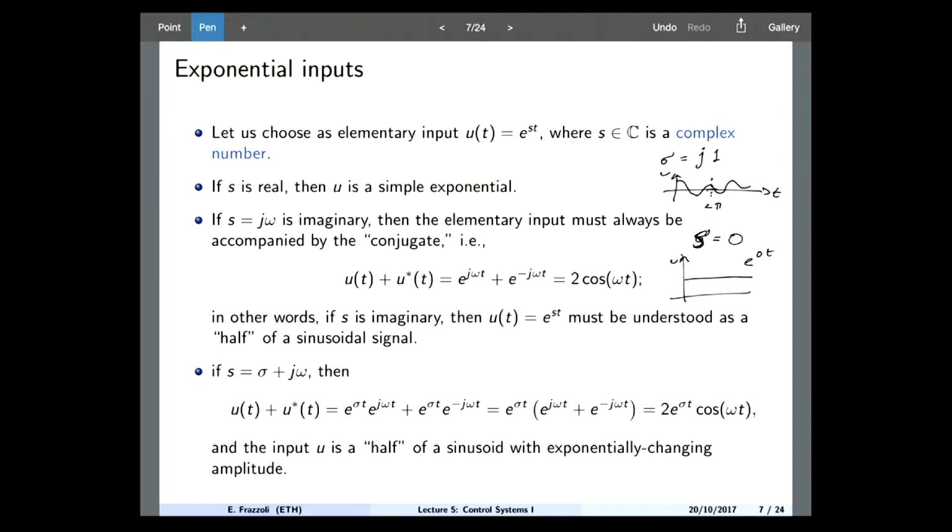You just multiply it. Remember that for linear systems, if you multiply the input by, say, a constant c, what happens to the output is also multiplied by the constant c. That's why, typically in control systems, we talk about unit step, because it doesn't matter. If you want the step to be 23.5, just multiply whatever by 23.5. Scale doesn't matter. Clear? Any other questions?